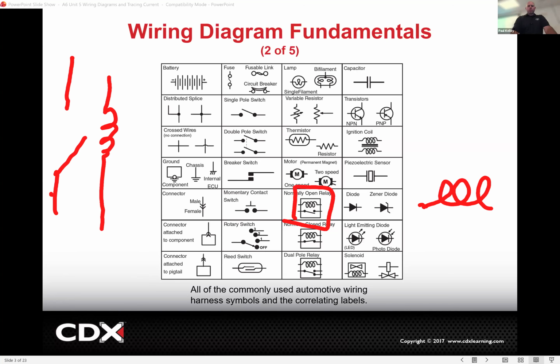If that was the load, just keep in mind as we do this, we should have 12 volts coming down. And what should we have after the load if it's working? It should be ground down here. Right, so just remember that part is an actual load.